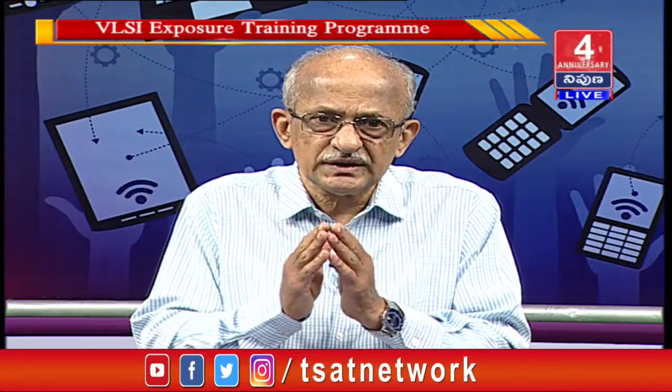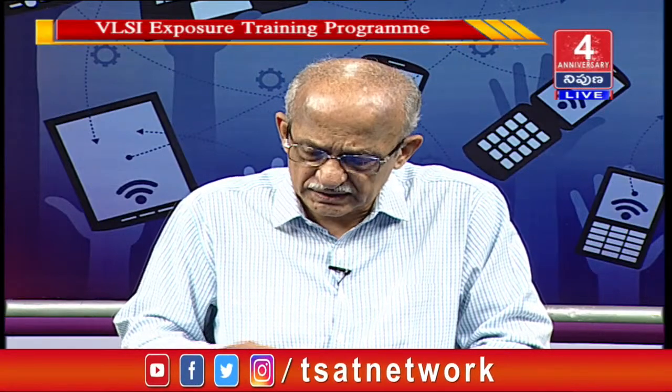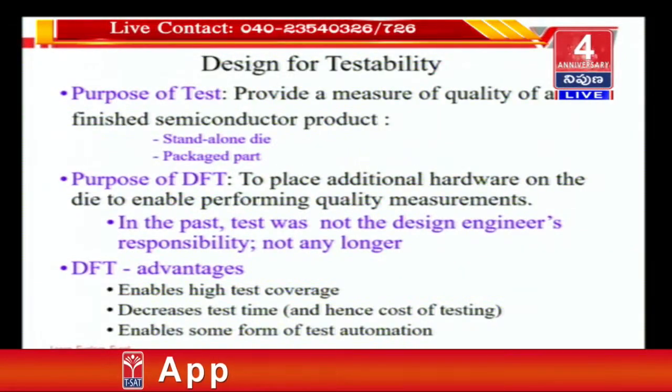So therefore every test vector, we call a number of bits put together a vector. Therefore a test vector is basically a test pattern that is applied in parallel to the circuit. So a test vector consists of a stimulus, which is the input, and the response, which is the output. A stimulus response pair constitutes one vector. Such test vectors are applied to the device, okay, and the device then gets tested on an ATE, also called the tester or the automated test equipment. It decreases the test time.